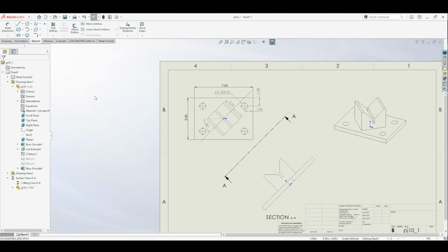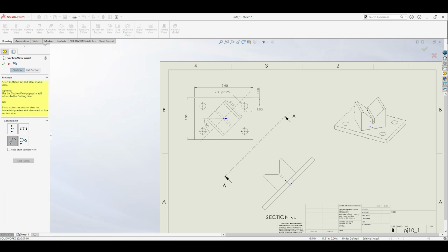And there's other ways to do sectional views, like what I was trying to show over here. There's a vertical one, there's a horizontal one. Auxiliary is for all the other weird angles like this. There's an aligned one where it takes a square, a perpendicular cut, and then something diagonal to the part.